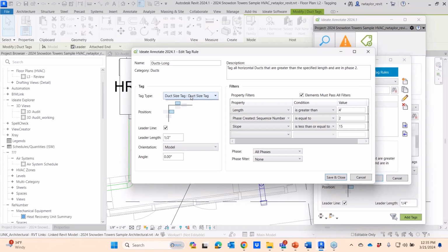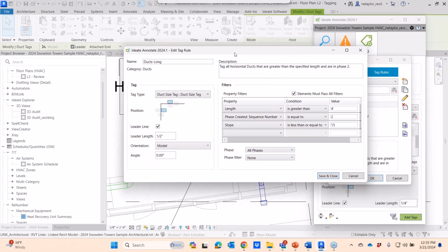This is the duct sizing. That's the only tag I really have loaded, unfortunately, in this. So if I had a tag that had text associated with it, like maybe the name of the duct, it should be rotated according to the model element using this orientation. Yeah, and there's the function within the family as well to rotate with component. That may need to be checked so that when you place the tag, it's going to rotate the same direction as the ductwork. Maybe that's the question.